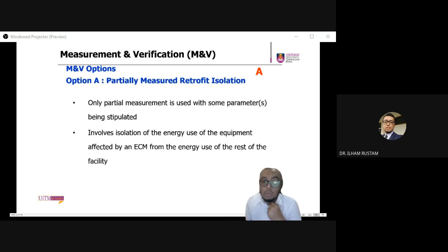So you isolate that machine by having their own meter, their own equipment, whatever is needed to realize your energy saving from the rest of the organization, so that you get the actual data for that machine themselves, not the whole organization. Because if you lump sum it up with the organization, chances are you don't know the actual energy being used for that machine.